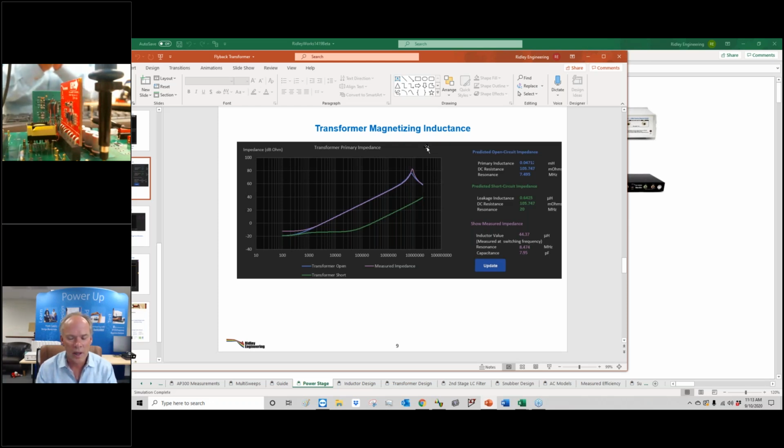When you've got that frequency versus leakage, you've got to use the leakage value at the right point. If you're designing the 10 megahertz snubber, you want the leakage at 10 megahertz. If you're trying to calculate 1/2 Li squared, you should probably use the leakage at 100 kilohertz. And the value the manufacturer gives you might be at 10 kilohertz, but these values are all over the place, a 2-to-1 range in difference. Somebody asked about the Ridley box or the AP310.